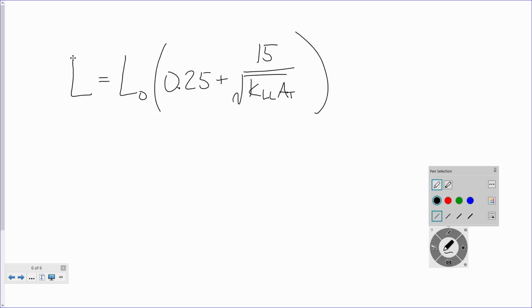For those of you that weren't exposed to this, this is the live load reduction formula used to account for building loads. To give you an idea, if I remember correctly, the design load for a classroom, let's say, is like 40 psf. I think it's 40. It might be 60, but I can't remember. To equate that in terms of people, the size of this room, to reach that design load, you'd probably need about 120 people in this room. When do you ever think there's going to be 120 people in this room? Never, okay? So the design codes specify a certain live load, but we are allowed to reduce that